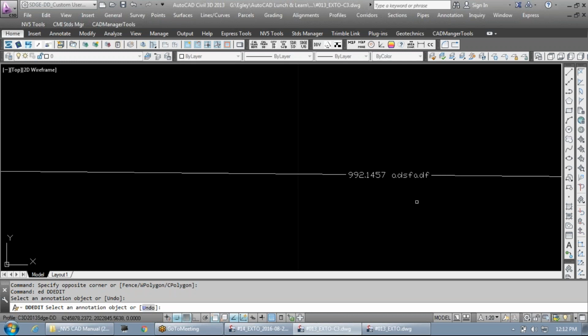For the gas group, as I think I mentioned to most people here, we are going to change the way that the title block is done. It's no longer going to be block attributes. They're actually going to be fields reading your sheet set. So all that title block information is going to be populated from your sheet set. And there's great opportunity to do that office-wide for the other groups as well, so that you're not managing all these block attributes in 20 different files and all this stuff. We just have it read one source, and that source is going to be your sheet set. So those of you who aren't comfortable with sheet sets, you're going to really need to become comfortable utilizing sheet sets. And hopefully everybody's using sheet sets, right?